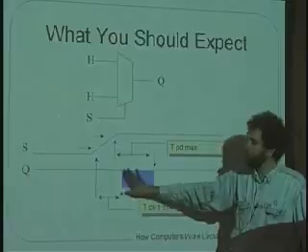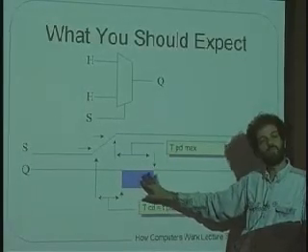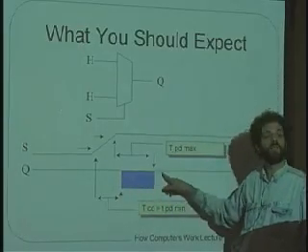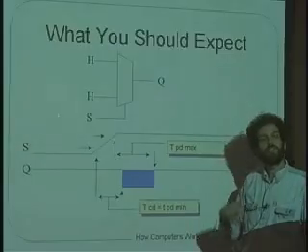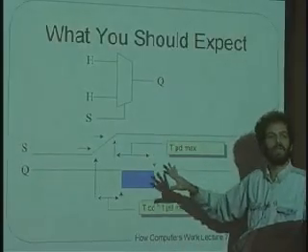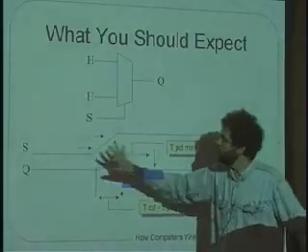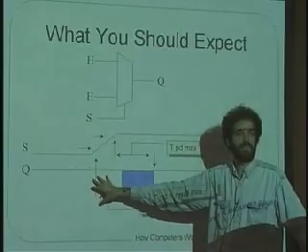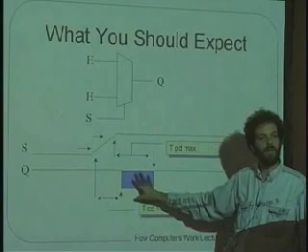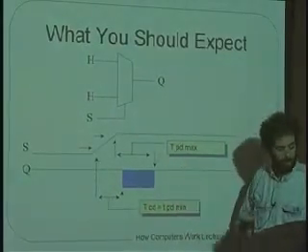So there's always going to be this blue time in the middle where, for a standard logic device, we don't know what the output is. And so the fact that there's a glitch during this time is kind of to be expected. In general, in most logic devices, we're not going to expect them to perform any better than this: if the inputs are valid, the output is valid. And if the input changes, then we go through this indeterminacy time, and then finally the output becomes valid again with the new output value.